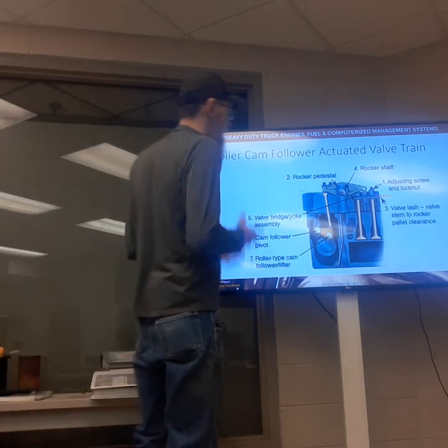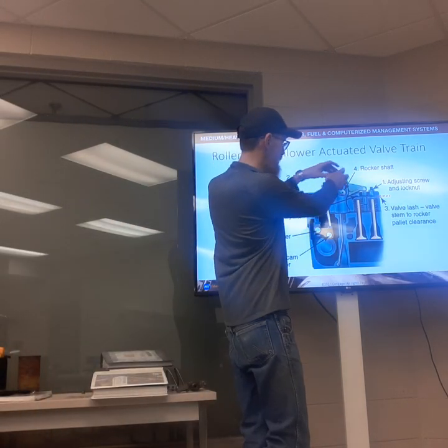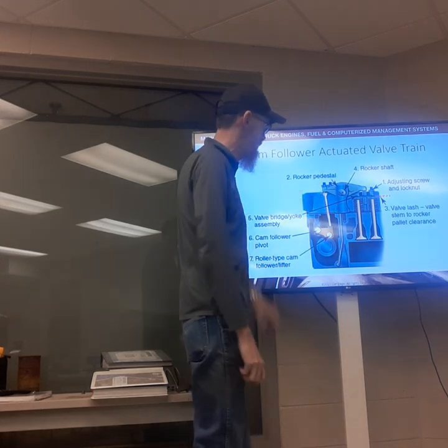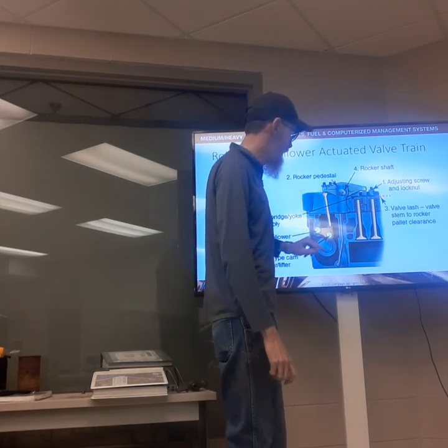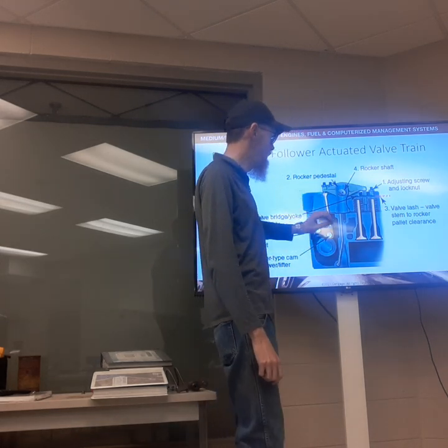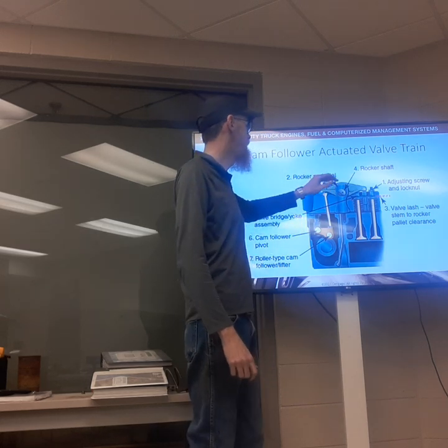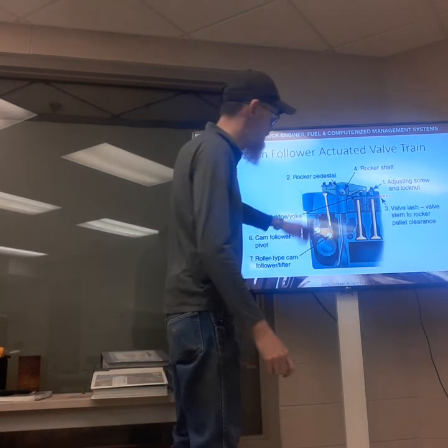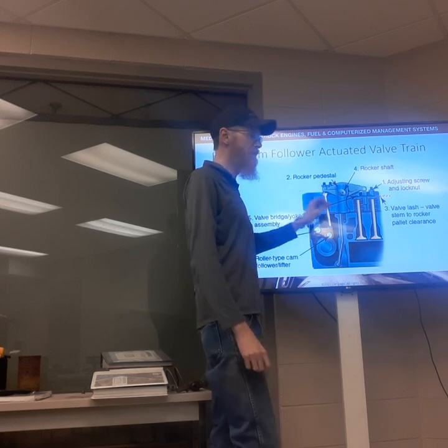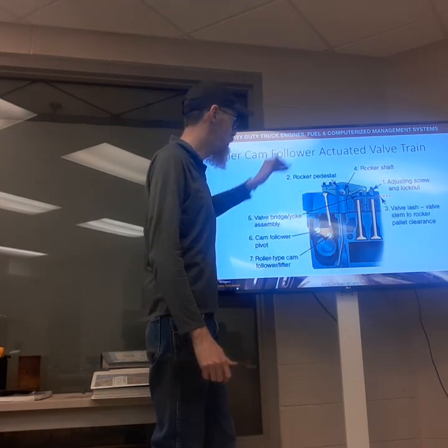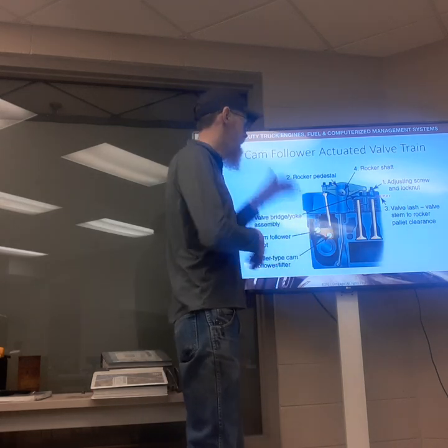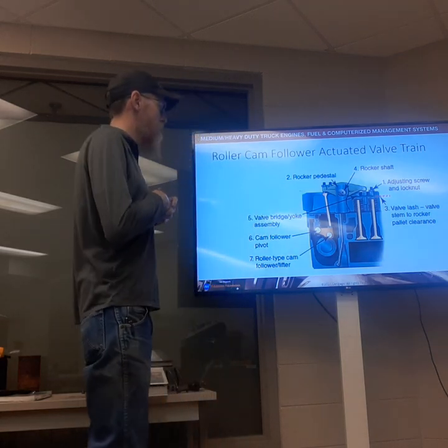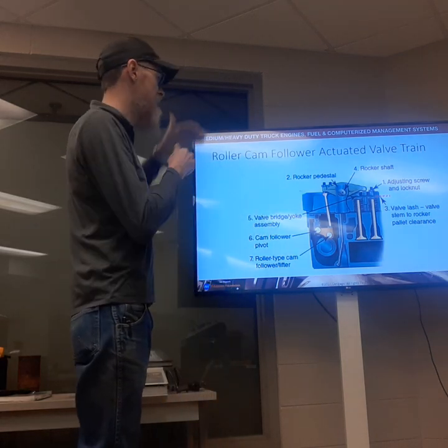By moving that camshaft up into the cylinder head, we get rid of that pushrod, and now our cam lobe is able to act directly upon the rocker arm. We also have some kind of cam follower in there between the rocker arm and cam to transmit that movement.